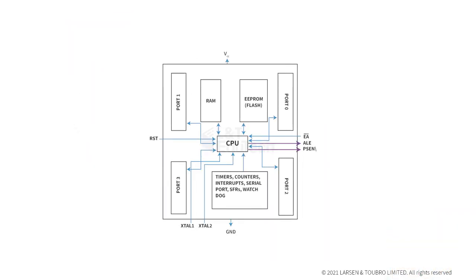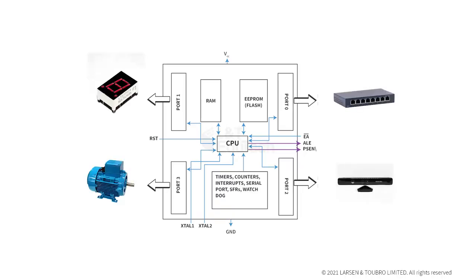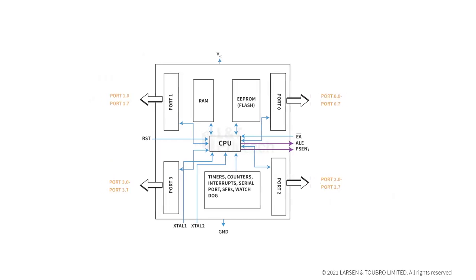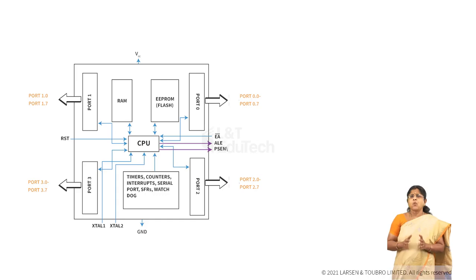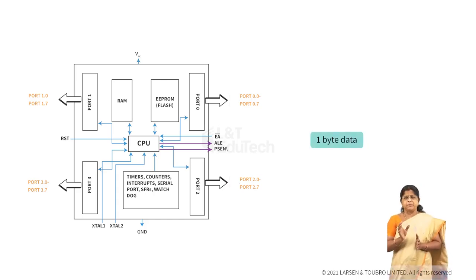Now our next focus is on I/O ports. I/O ports are required for interacting with external devices or machines or peripherals in any real-time applications. Using I/O ports, we can control and monitor the hardware. In general, the I/O ports are 8-pin ports. This gives us the comfort to access 1 byte of data, which is of 8-bit length in the 8-bit microcontroller.